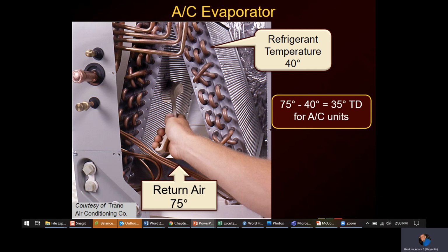The hard part of that is a lot of times you can see the top of the coil, but usually the top's going to be pretty clean. Unless it's like a mobile home that has a coil sitting on top of it and it's pulling it down, a downflow, usually you can't see the return side of that coil where it's actually pulling the air into. So you'd either have to take that cover off like they've done here, or take the door off and see underneath of that coil, but most of the time you've got a line set hooked up and pipes and other things hooked up.